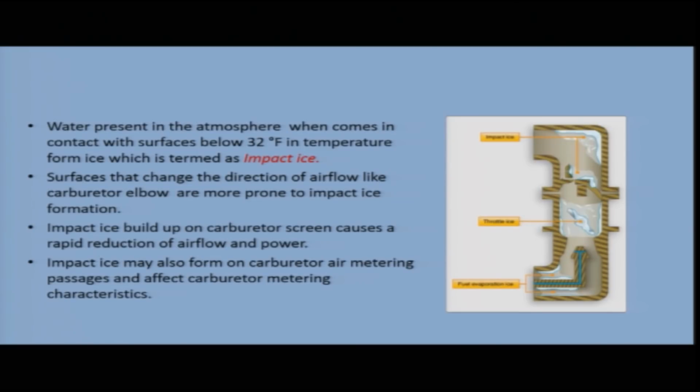Impact ice buildup on the carburetor screen causes a rapid reduction of airflow and power. Now, in case the impact ice formation is taking place on the carburetor screen, then there will be a rapid reduction of airflow and finally there will be rapid power loss.